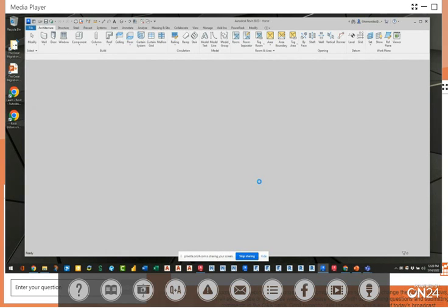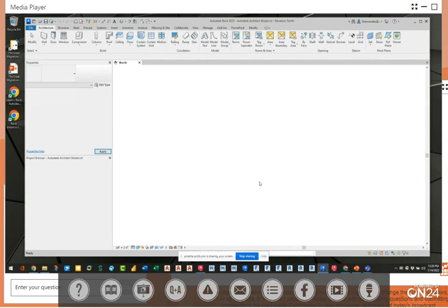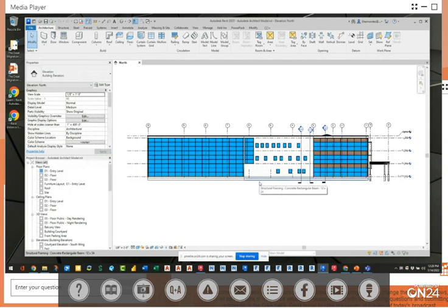The audit basically scans and detects corruption in the project and fixes it. That's pretty simple. But there's no report to tell you, hey, Gabe, this is what it fixed, or this is what it repaired, and these were the families that were causing the problems, right? So that's unfortunate, but at least get into that as a good habit.